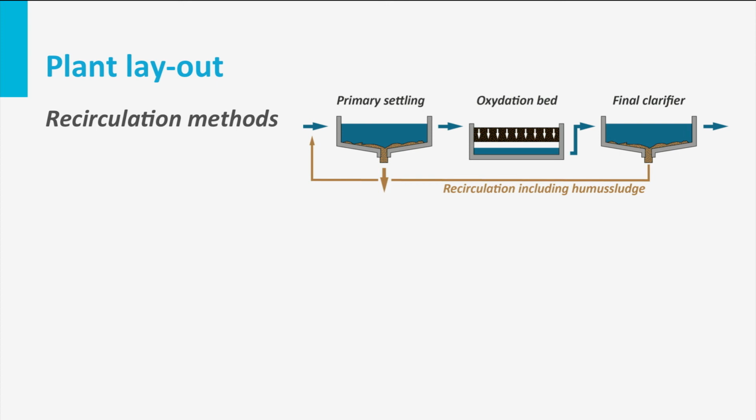Recycling can be performed by pumping the secondary sludge with the nitrified effluent to the primary clarifier. The overall excess sludge is then withdrawn from the primary clarifier for further treatment. The oxidized and nitrified effluent facilitates odor control in the primary clarifier and the trickling filter. When connected to a gravity sewer, the primary clarifier is preceded by an influent reception basin. In such case, the recycled secondary sludge will be added to the reception basin for enhanced odor control.